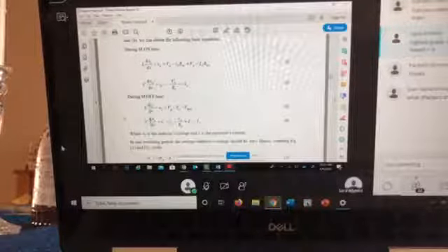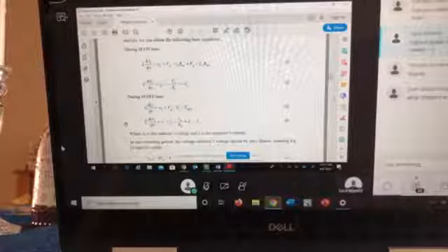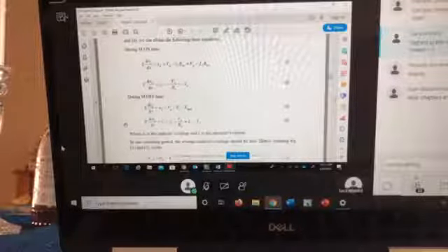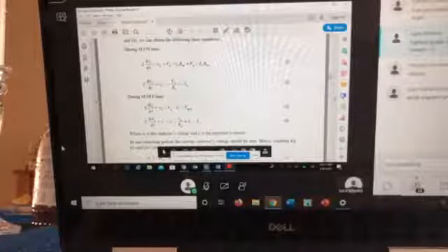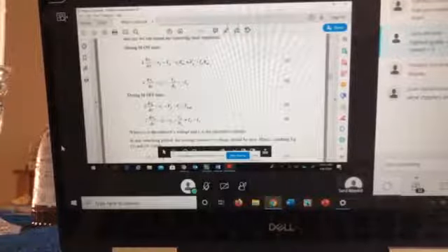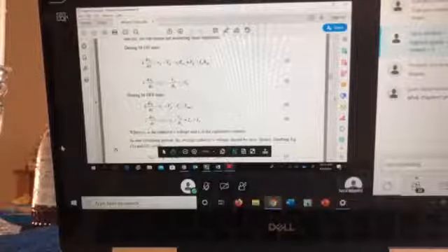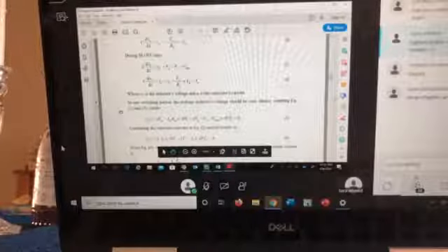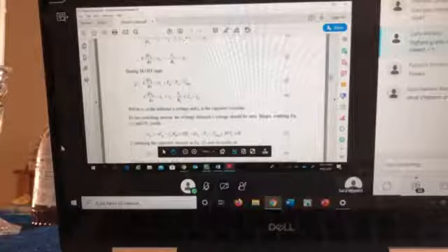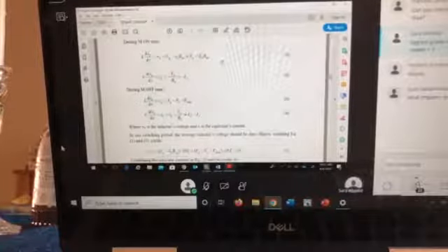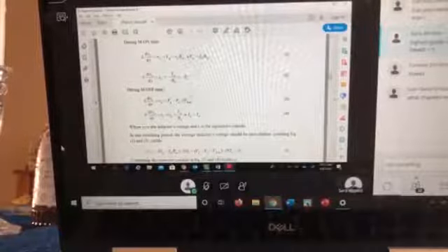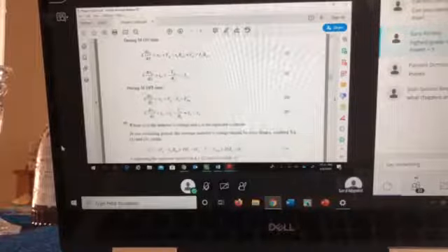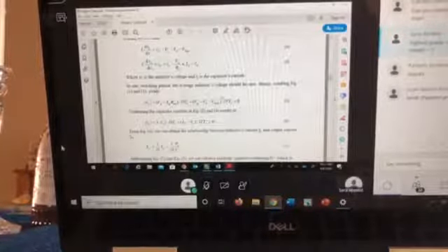With those two equations, if I want to get my duty cycle, I need to do inductor volt-second balance, which means the average of the inductor voltage should be 0. Let me hide this one. It should be 0, right? So I'm combining those equations, the equation when the MOSFET is on and when the MOSFET is off. This multiplies by dTs and this multiplies by d prime Ts, and we equate it to 0. So we do that.